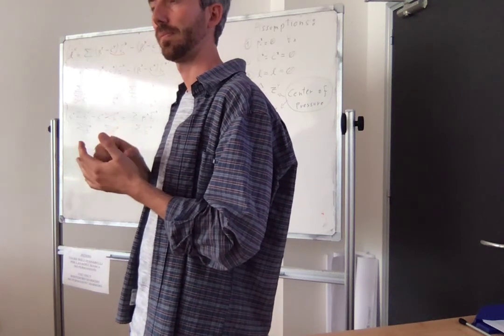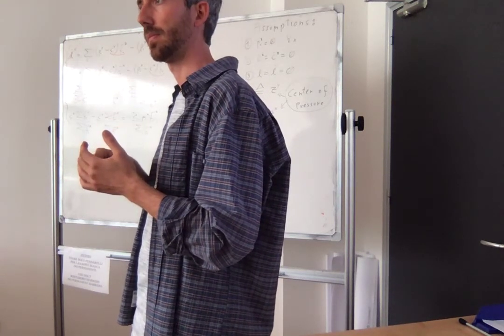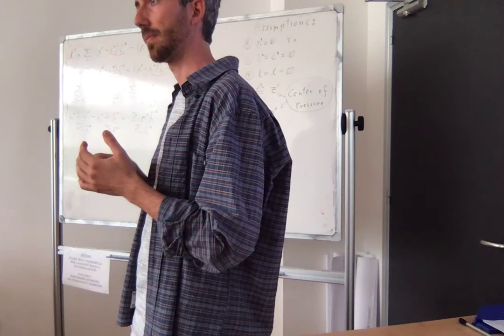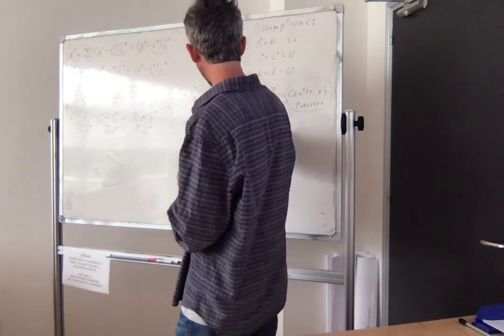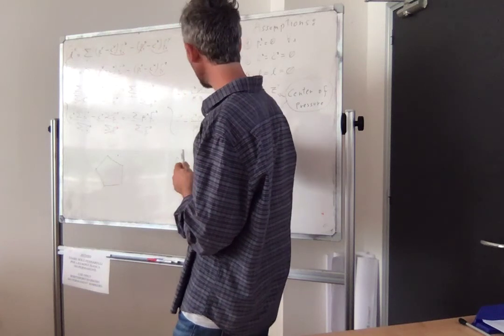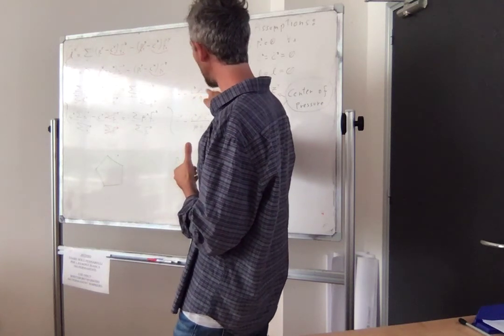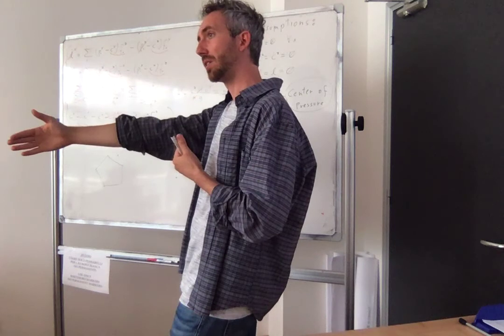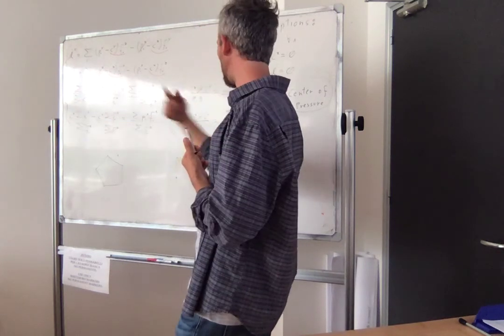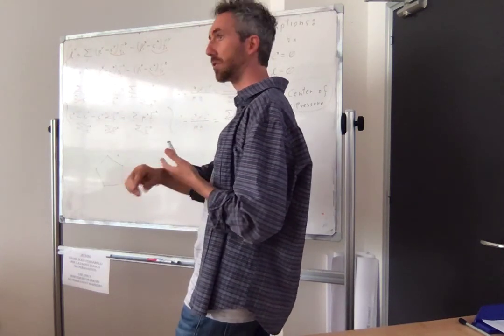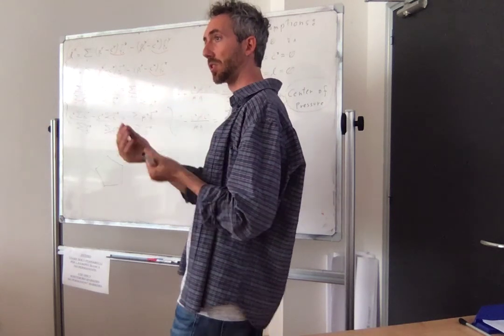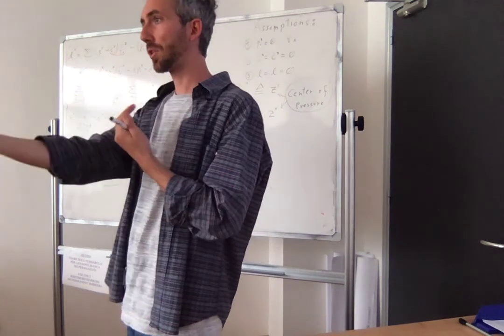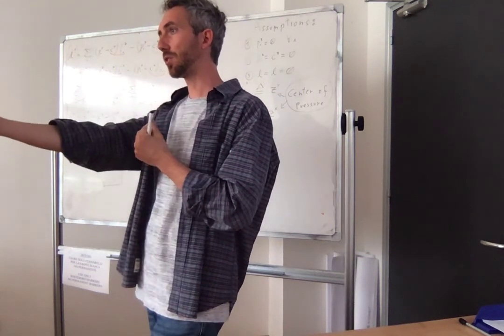So that equation represents a point that follows the center of pressure with a second order system. So this is really the center of pressure, and the center of mass actually is pushed away. I will show you better next time, now it's late so I stop here, but this is an unstable dynamics, so the center of mass is pushed away from the center of pressure.